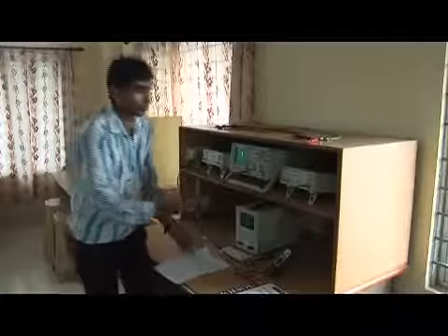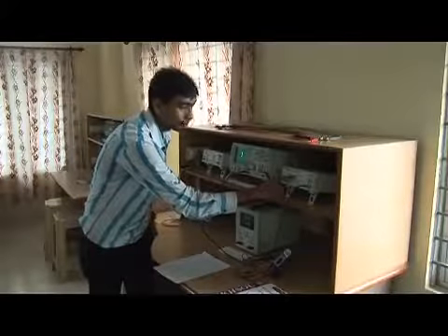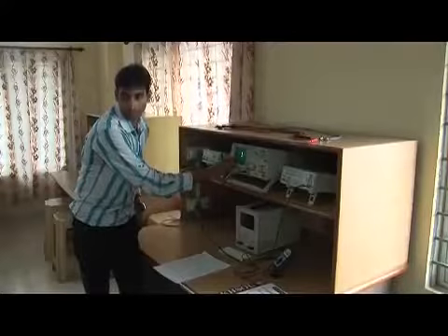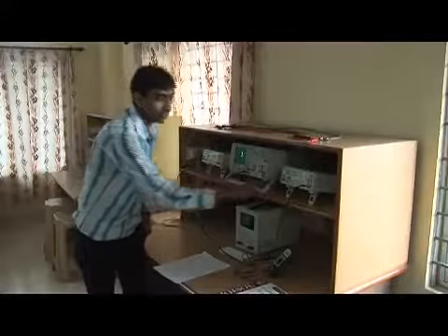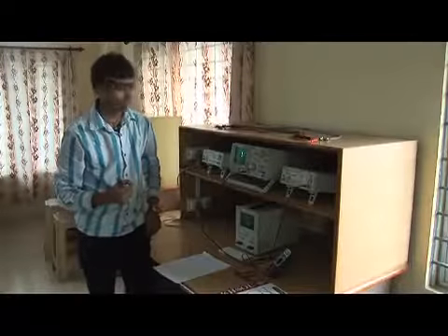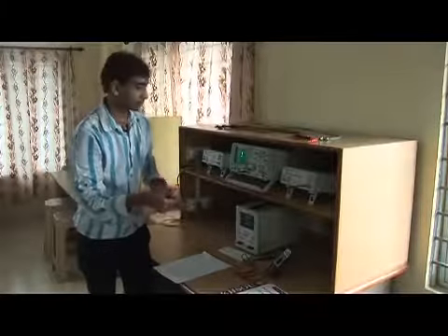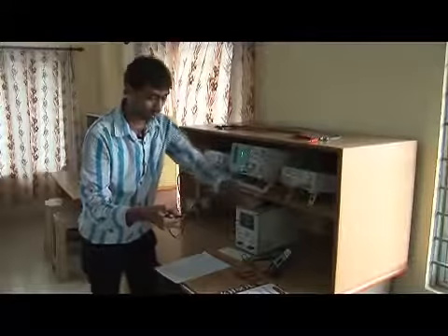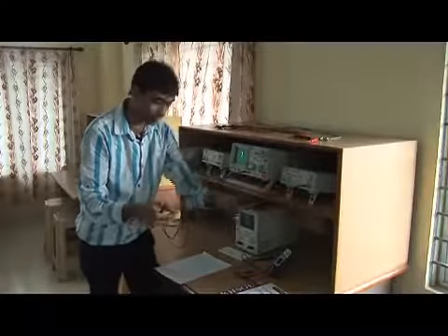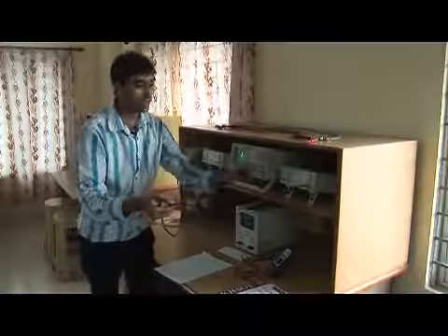So you have the amplitude of 1.9 volts, but how much amplitude were we giving? 2 volts. So this 2 volts is coming down over here to 1.9 volts. Why is the difference there? You might have heard about different resistance losses. This wire has some resistance. You are using a big wire, so this wire has various resistance. So what happened? Whatever has been generated, due to the resistance of this wire, some part has been dropped here.